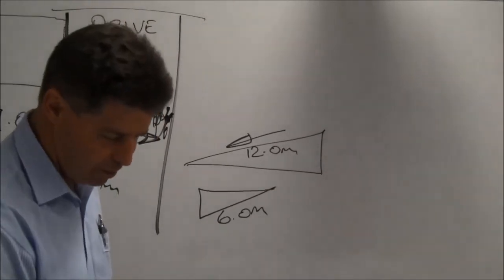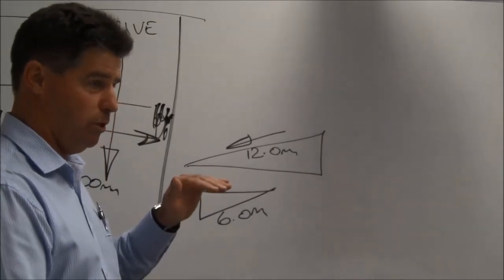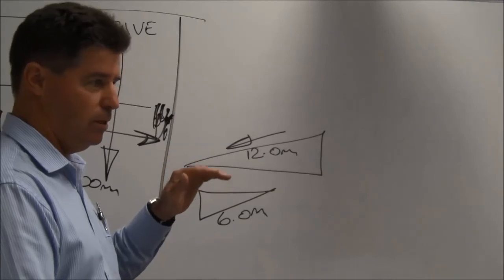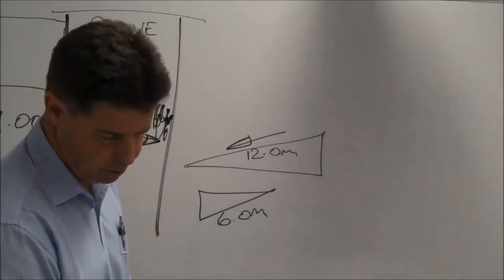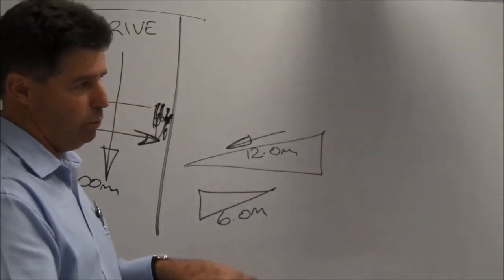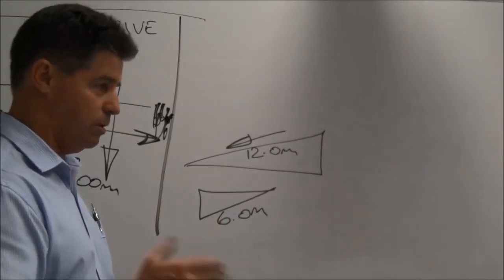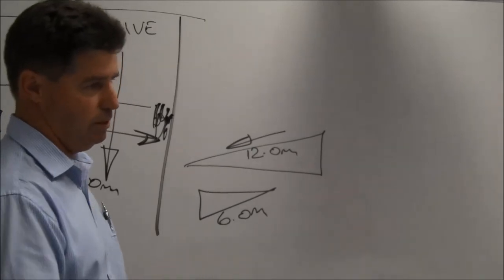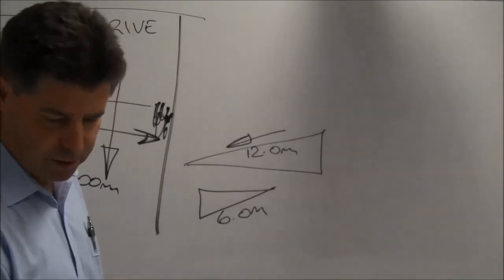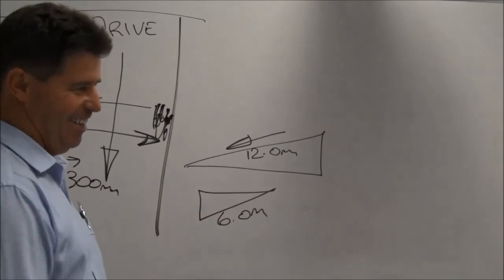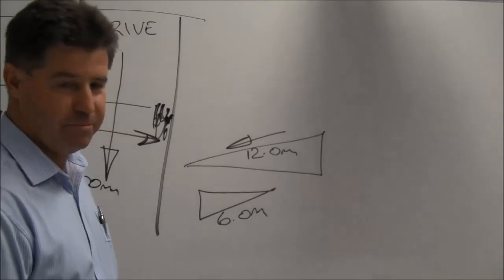Generally, it works with most surfaces. Also, the CSIRO, I think, have a building research list, and I think they're exactly the same numbers. Sometimes they give surfaces between 0.011 and 0.015, for example, so you can either work with the best or the worst. It depends on the finish of the concrete. If it's honed, obviously you can use a better number than if it's just float finished. But again, we don't design to that. Give yourself a safe margin. Just as a starting point.